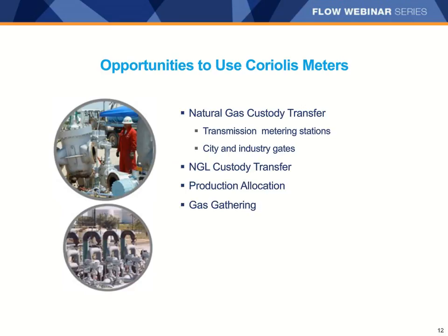Natural gas cavern storage is another good application for Coriolis meters for many of the same reasons mentioned earlier for custody transfer, but also because the meters work in a bidirectional fashion that cuts down on the amount of piping and valves needed. Coriolis meters are a good way to manage buyback of residual gas for treatment plants when fluctuations in supply and demand cause the plant to need to pull back some gas for ramping back up to capacity.